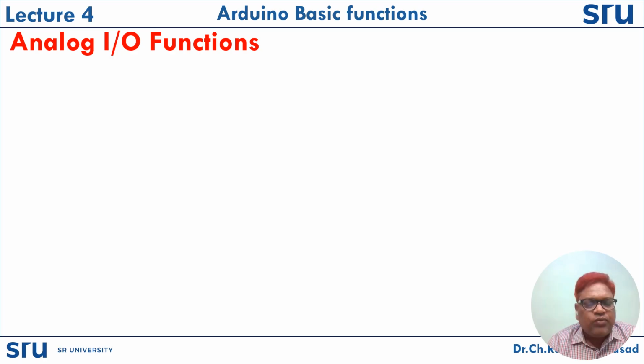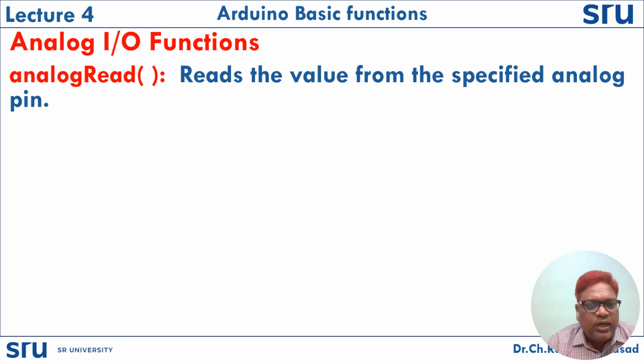Coming to analog I/O functions, for analog I/O there is no need for programming. Why? Because they are separate lines, and by default they act as analog inputs and analog outputs. So we have analogRead and analogWrite functions only here. First we need to see analogRead. This function reads the value from the specified analog pin.